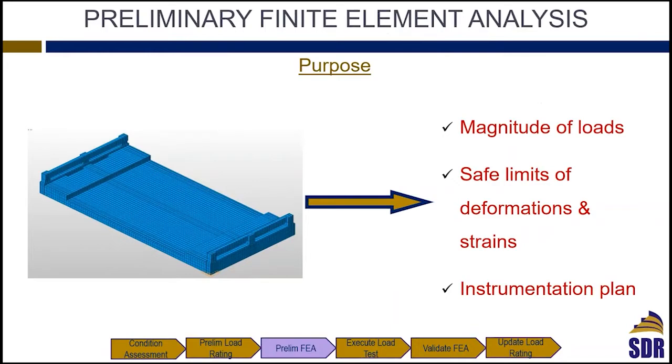After that, before going to do the actual test, we have to start developing our detailed finite element model. At this stage, this model serves several purposes. First of all, is to determine the magnitude of loads that we can put on the bridge. We cannot just go in the field and get a heavy truck and put it on the bridge and end up damaging the bridge while testing. So that's a very important point. We have to determine what is the magnitude of the loads we can impose on the bridge.